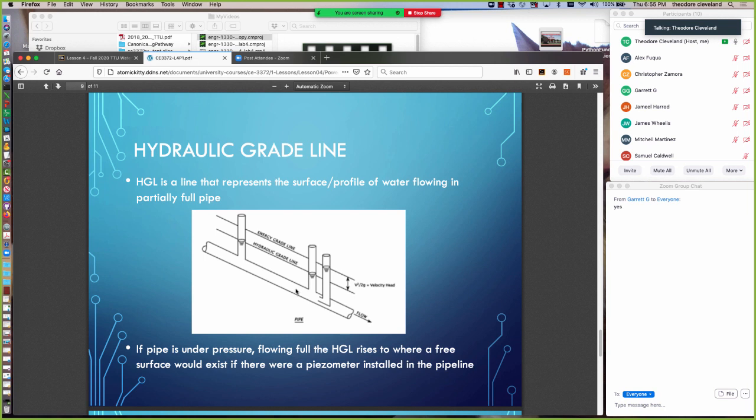And because the water's moving, the velocity head stagnates and provides a little extra elevation here in the pitot tube, and the difference between that height and the height in the static tube in the piezometer is the velocity head. So velocity head can be measured, the alphas can't, but it's not routinely done. Certainly not in a water pipeline.